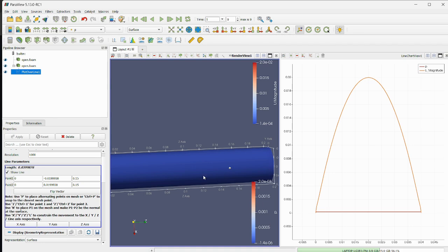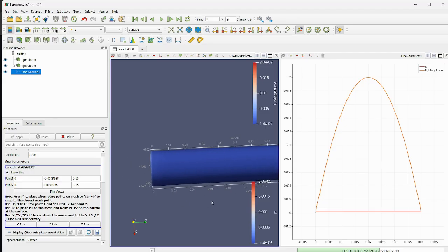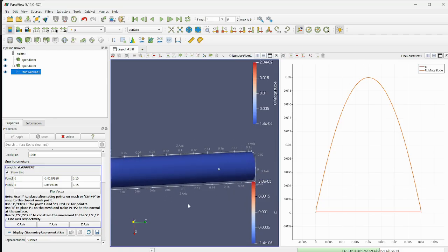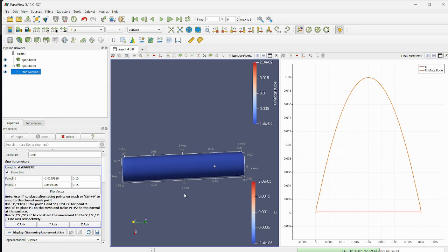So yeah, this is where it's important to know Reynolds number and entrance length, because if your inlet velocity is too high or your dynamic viscosity is too low, then you're going to have turbulent flow and you're not going to get this nice looking parabola. Or if your pipe is too short, or you're taking your line scan too early onto the pipe, you're going to get a blunted parabola, just because you're taking a scan across a region of the pipe where the flow isn't fully developed. So I hope that made some sense. Anyways, on to the post-processing.